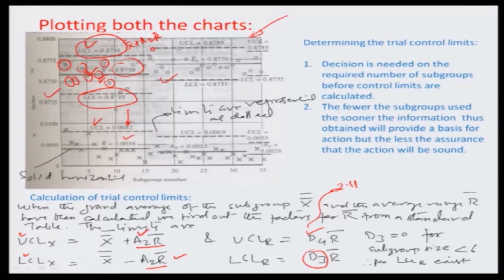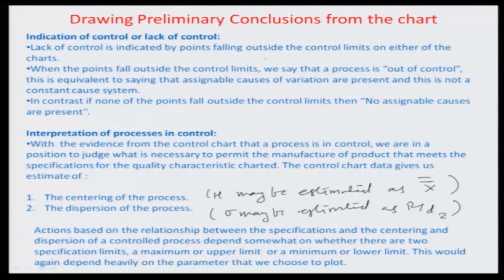And similarly from the range chart also, they are quite variable in terms of their mean or the UCLs or the LCLs and how far they are away from the mean, and obviously a tighter control or a better control can be reflected in probably the second case here, because it is accommodating for that factor of post cooling recording of the milling slot width in question. So, I think this is giving you an idea of how the control charts can be plotted.